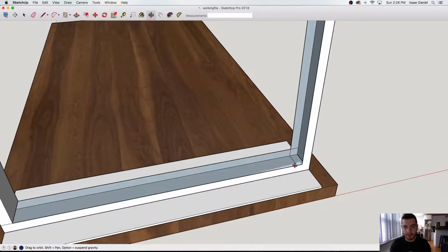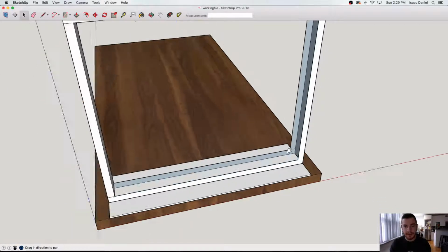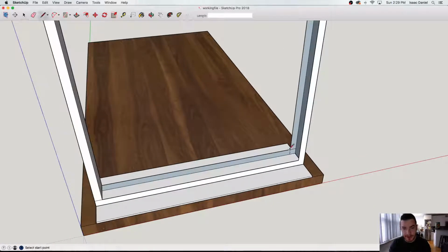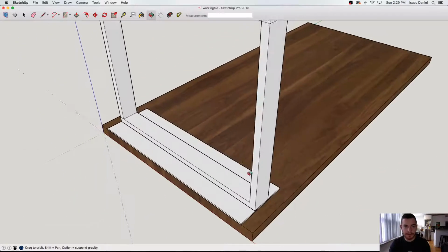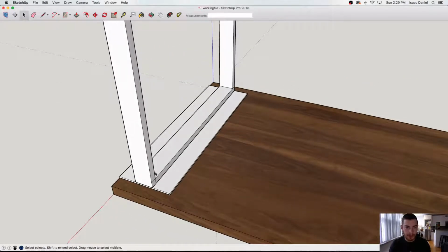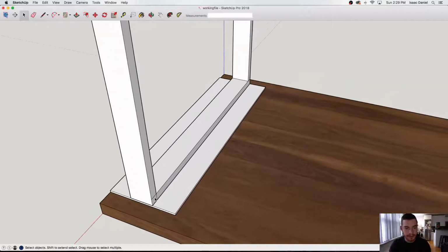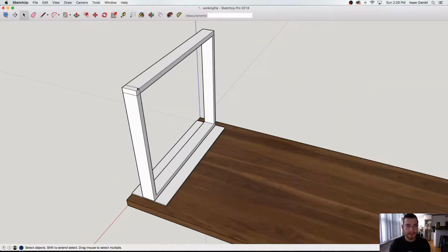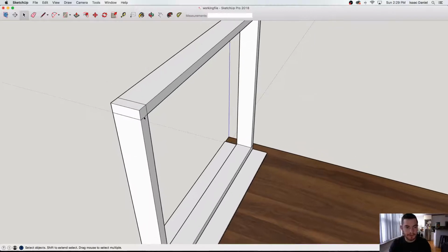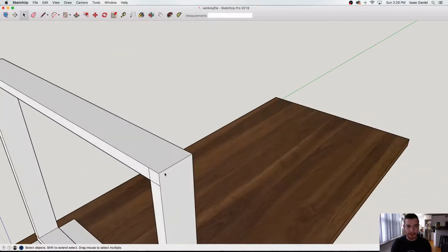say, oh, I don't know what you're doing there because you've created new geometry. If that happens, usually what's missing is just a line for SketchUp to understand. So we'll draw a line back in there, and you can see the faces are now back. You can select line in the shapes. I just use L for line. SketchUp's pretty straightforward. If it has a shortcut, it's usually based on the first letter of whatever tool you're using. And you can just delete these lines. I accidentally deleted a face there, but as I said, SketchUp's pretty easy. Finish the geometry and it'll bring it back.